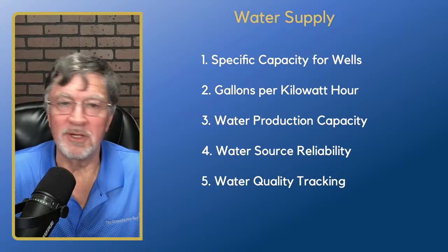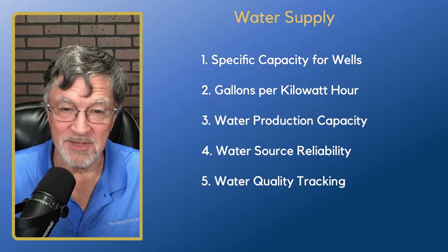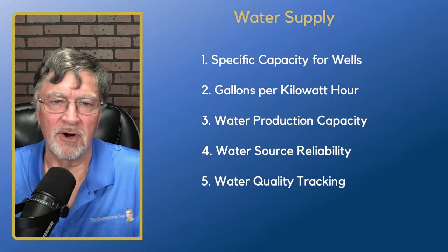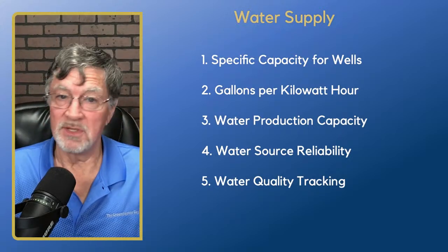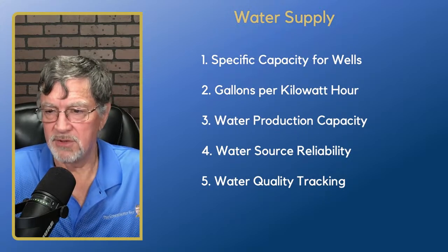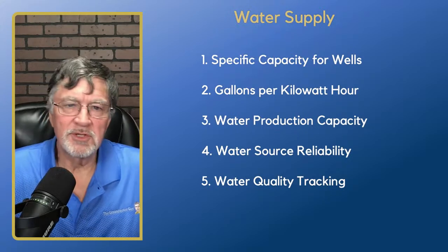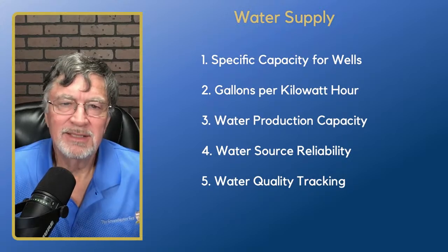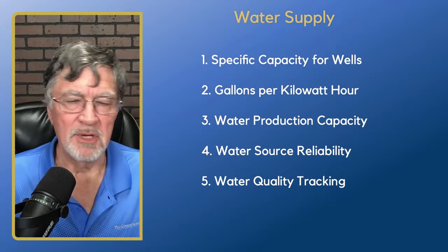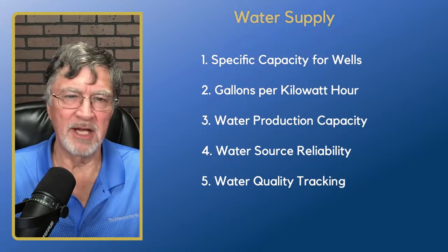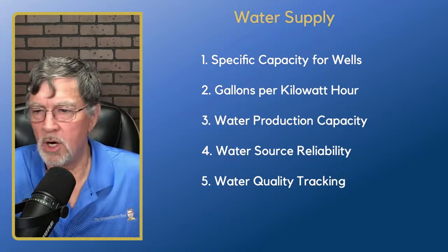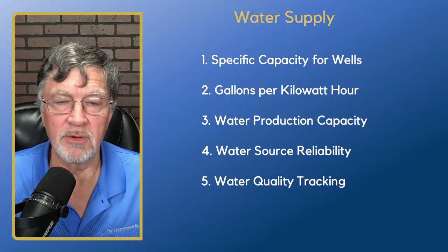And they really should be looked at. You've paid for that data, you've paid for that testing. You should really be taking those results and plotting them up in a chart and tracking them, because it's data that you already have that you paid for. Why not get some use out of it? So for instance, you can say, okay, this should be obvious, but it may not necessarily be so. You get changes in management and personnel. So really, what percentage of our water quality tests are meeting regulatory requirements?